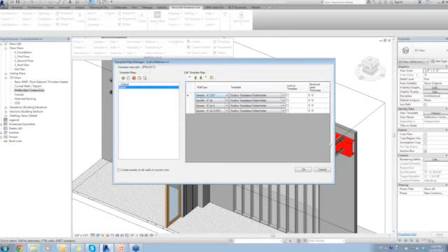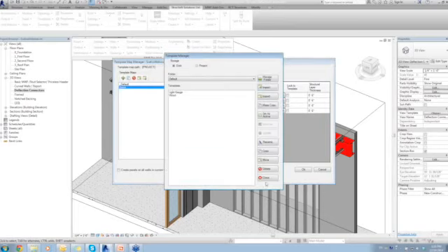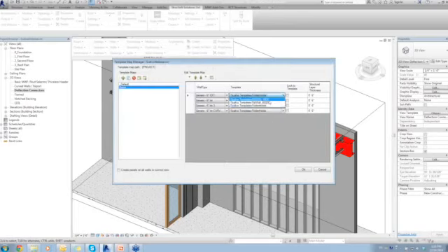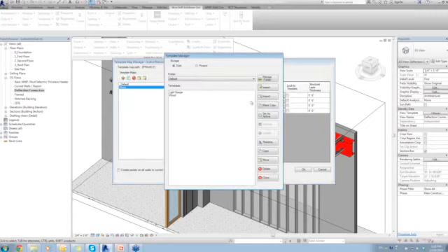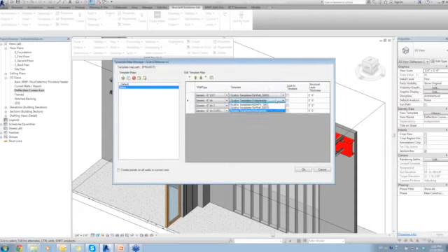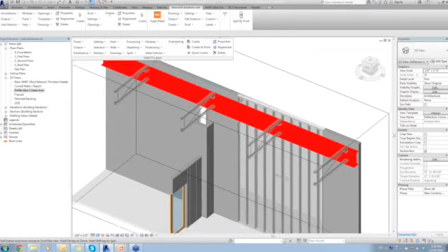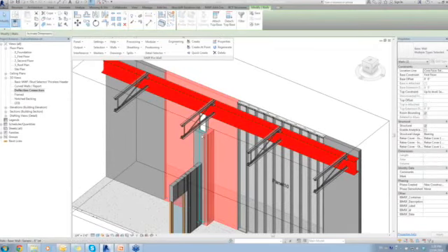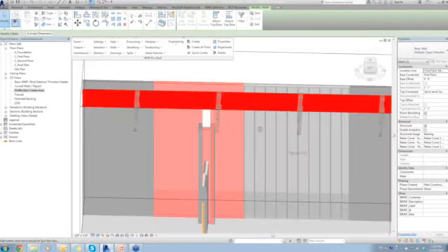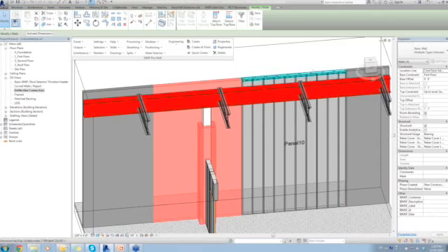So I have that generic 6-inch exterior wall, and I've already created that 600 exterior wall template, and I have a couple of interior walls that I made that template for right there. We'll come back to this curved wall after when we look at our perfect curve products. Now I can select an array of walls, no matter what their wall type. If they're multiple categories, it's not a problem.